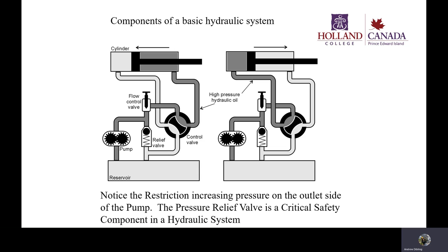Okay, so the flow control valve here will meter the fluid down. The relief valve is designed, as I mentioned before, to provide a pressure relief if design pressures are going to be exceeded or pressures such that could damage the system. Sometimes you'll get them go off as well if you've had a big load shift. Three or four things shut off at the same time. That can take a pump that's been running very hard and all of a sudden give it a large restriction, which will drive the pressure up. That may temporarily pop your pressure relief valve.